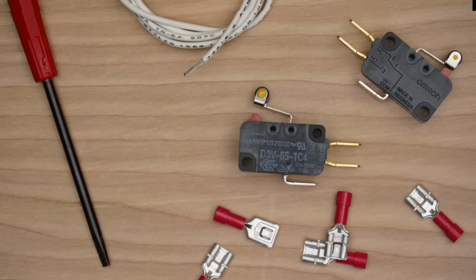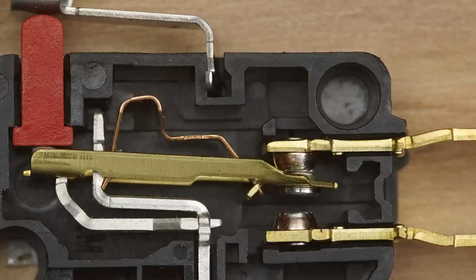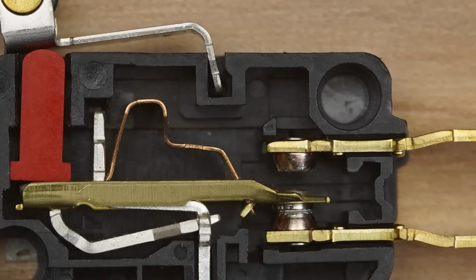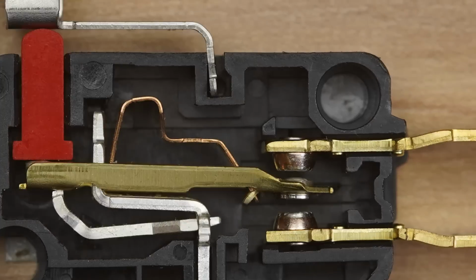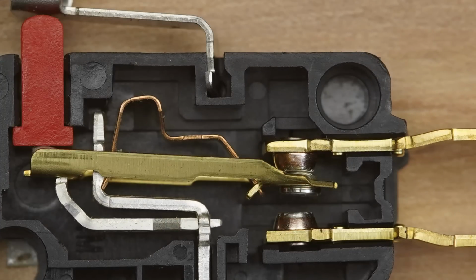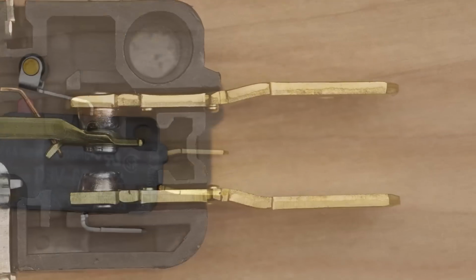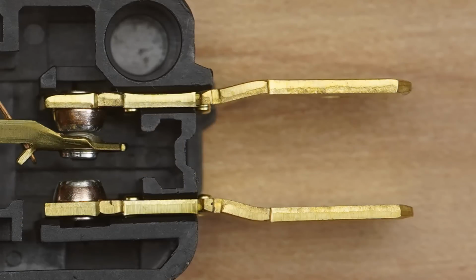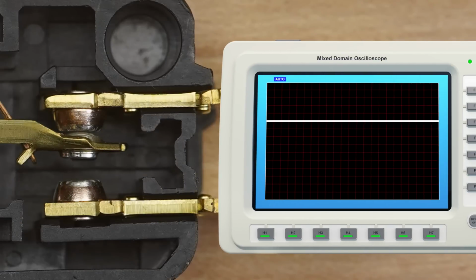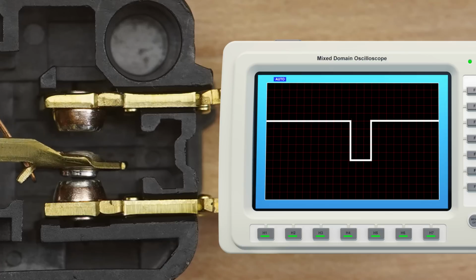Switch bounce is a mechanical action that occurs when any type of switch contacts are pushed together, causing a rapid making and breaking of the connection that can last several milliseconds before the contacts come to rest. Think of a ball bouncing on the ground, getting lower and lower until coming to a stop. Because switch bounce is not typically visible to the naked eye, connecting an oscilloscope to the switch reveals precisely what is happening to a signal passing through the contacts.